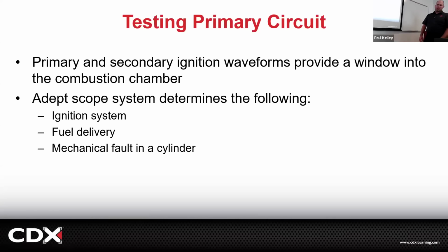And then measuring the primary is pretty easy because the primary is low voltage. Sometimes it's good to measure the secondary, but the problem is the secondary voltage. Remember how that's like 20,000, 40,000, something like that. Your oscilloscope's not going to go for that. Your oscilloscope's going to be like, I'm done, I quit. Let the magic smoke out. You zapped it, right? So we're going to mostly focus on, at least for now, the primary circuit, simply because it's easier for the oscilloscope to deal with. And a lot of times it's easier to actually connect to and measure, okay? Because those are the small wires, right?